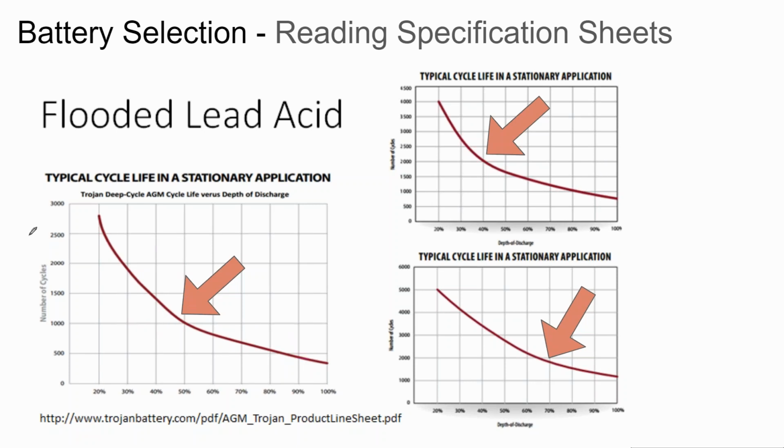What that also means is you are going to be oversizing the battery a little bit. The point I wanted to make, which I don't think we really touched on yesterday, is if you go for an average daily discharge of, say, 40%, that'll give you maybe, let's just call it, 1,300 cycles. Instead, if you oversize the battery and hit an average daily discharge of 35%, you're going to get a longer life. You're going to get more cycles out of the battery.